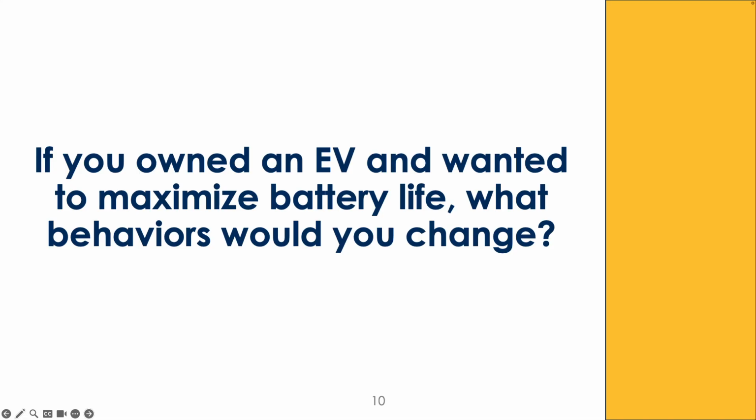Actually the vehicle tends to like it slightly hotter, so the 80 to 90 degree ambient temperature range is better. Once you're over 100, or operating below, say, 50 or even 40 degrees Fahrenheit, you will see that the battery operation is degraded a little bit and the degradation does accelerate.